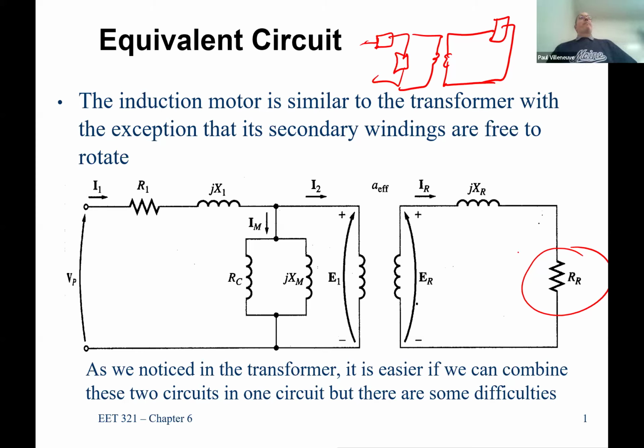Yes, sir. Do you have to do anything if there's an efficiency there? If it's the mechanical load, that's the output power, right? So that's the mechanical output. It does not, and this is a very good point that you bring up, Reed, it does not include friction and windage losses. That's separate.